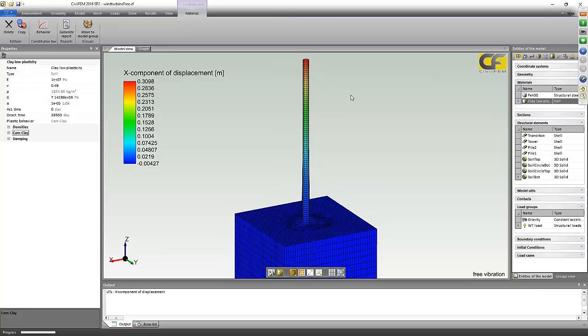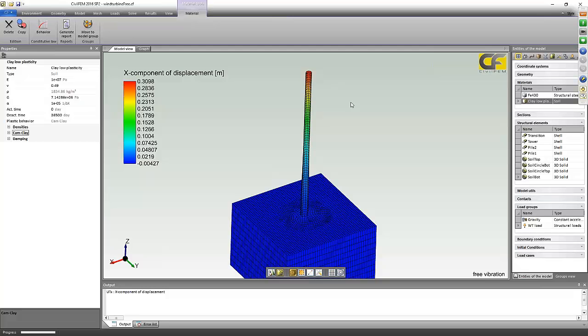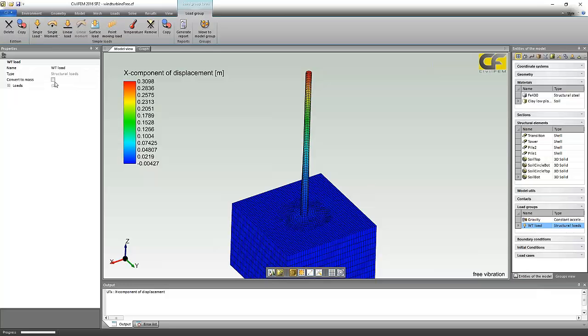Well, another important part for this dynamic analysis is the gravitational loads. The gravitational load masses shall be taken into account. With CivilFEM, it's very easy to model these added masses to the model. The way to do that is to convert forces into masses. First, we define any sort of loads with any sort of shape. Here in the pile could be the hydrodynamic masses of water, but we will see another example that is much easier to understand, that is with the hydrodynamic masses of a dam.